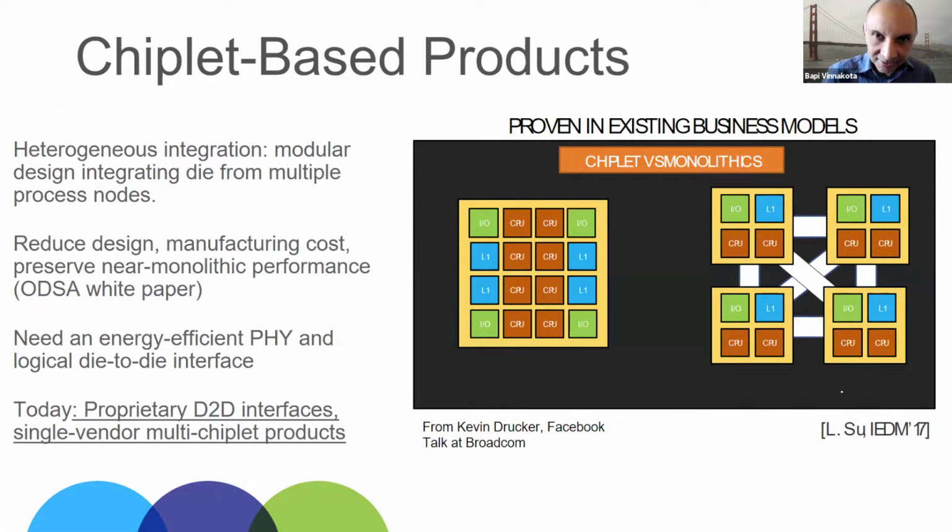So instead of making a silicon product from a monolithic die, you are making it as a package, a collection of multiple die in one package. And there are two or three motivations for this. One is you're disaggregating a large die for yield, or the second is you're trying to promote modular reuse, where you're reusing components. And this goes back to each kind of function being suited to a particular process node, being most economically manufactured at a particular process node.